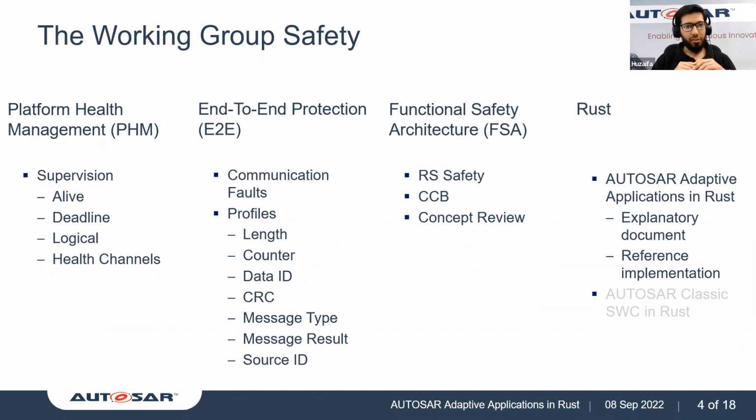The kinds of supervisions that we do are, for example, a live supervision, where we check whether the supervised entity is stuck or is still working. Then you might have deadlines for performing specific tasks that could be supervised as well. Moreover, a control flow logic could also be supervised.